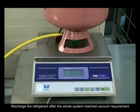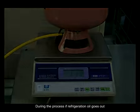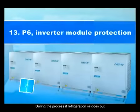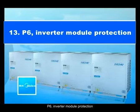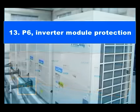Recharge the refrigerant after the whole system reached the vacuum requirement. During the process, if refrigeration oil goes out, you should charge a suitable volume of refrigeration oil. P6. Inverter module protection.